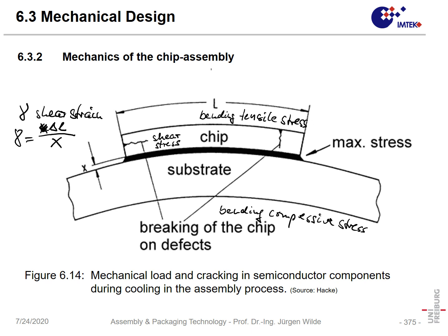That's the displacement parallel to that plane we have here. Okay, so shear is important, and so both parameters, the length and the thickness of the die attachment, can have an effect.